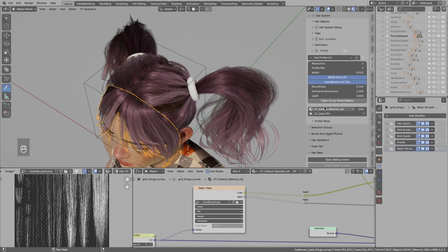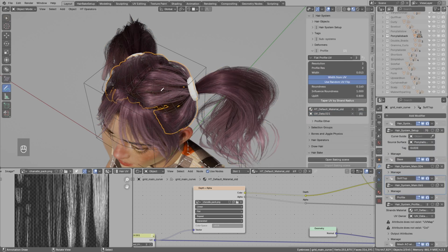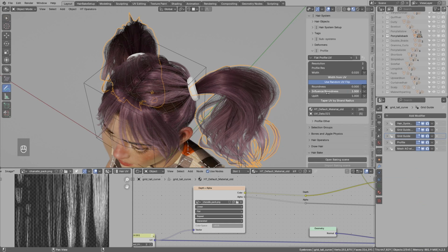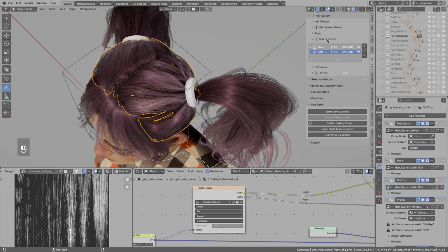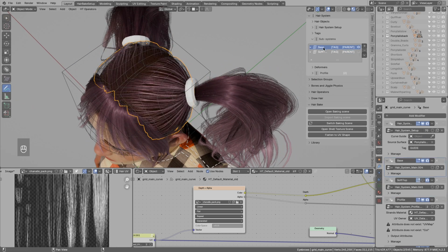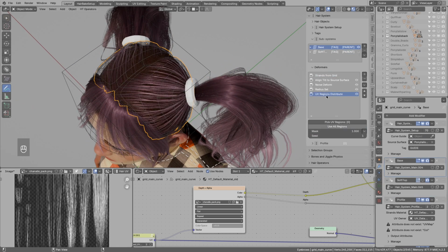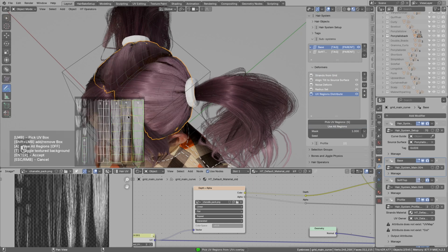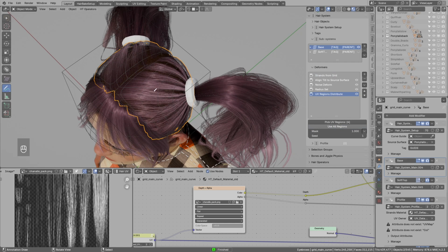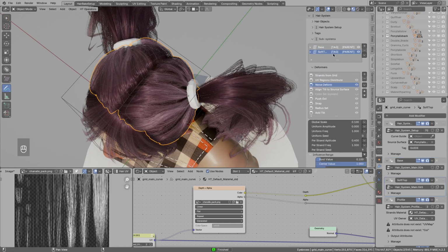And same in here, I would manually copy UVs. If you are lucky, all your hair strands will use the same profile, so you do not have to do this. And now it is just the same steps all over again. Go to base layer, search for UV region distribute, maybe pick a different region, enter to accept, and again second layer, UV region distribute.